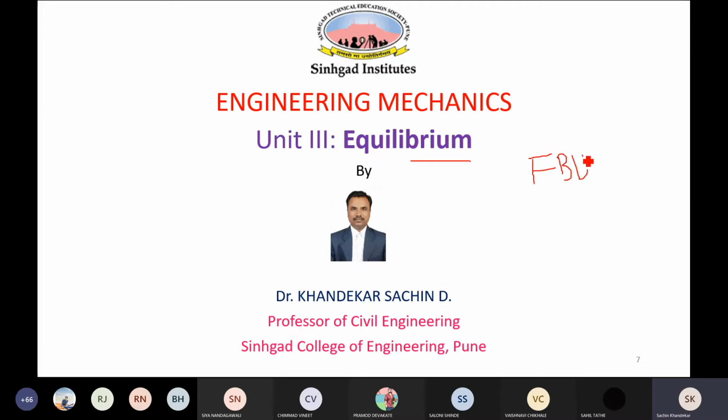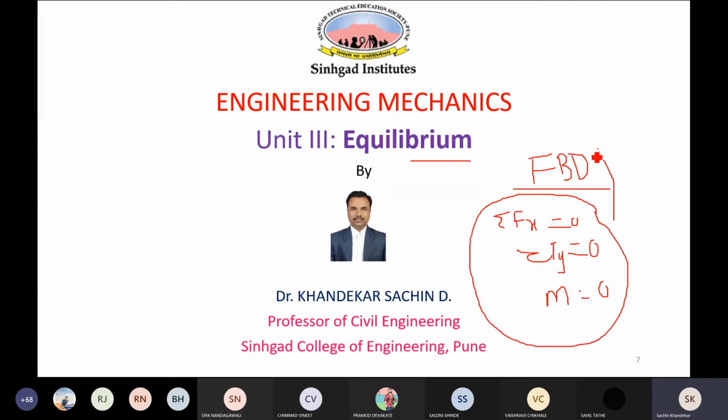Then after drawing the free body diagram, you apply the conditions of equilibrium, that is summation Fx is equal to 0, summation Fy is equal to 0, and summation moment is equal to 0. These three conditions we apply to the free body diagram, and then we can find the unknown reactions or unknown forces. These three equations are called the conditions of equilibrium.